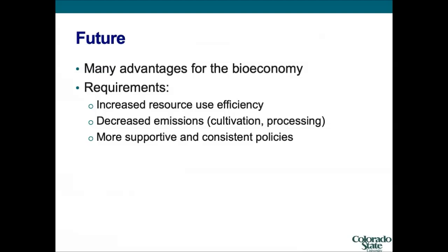Right. And what kinds of systems? Yeah, so really at this point, the only one that I know about is to use hydrothermal liquefaction. I don't know if you're familiar with that, but it's basically you take wet solids, which are ideally coming out of things coming out of a fermentation unit, for example, and then you subject them to what a chemical engineer says are moderate temperatures and pressures. That's probably not what biologists would think of as moderate, but a few hundred degrees C and a few atmospheres of pressure, and then basically you just turn it all into a soup.